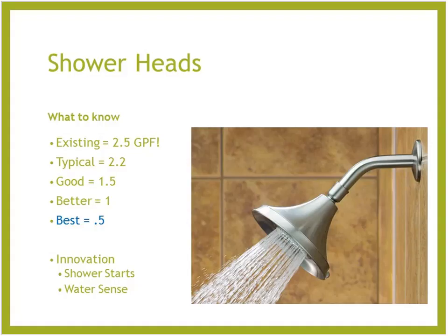Innovation: there are shower start devices that essentially let the water just drip a little bit. This is more for energy. Once the water heater heats up and gets hot water to the shower, it can be activated, and if you walk away, the shower start stops it. There's also some really cool technology out there that is supposed to get the flow rate really low and still give you a shower that you don't even notice is any different. And then of course look for WaterSense certification for your clients.